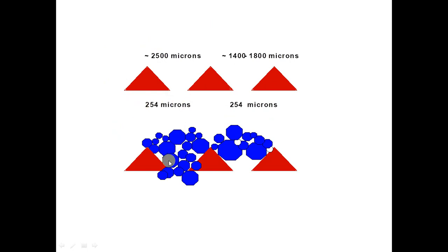Here, as you see, for example, if we assume that all of the bridging material is of the same size, as big as you can, like this, then at this time you will see a lot of voids between the large particles, and so it will let the filtrate be very high. But if we make a blend or mixture of the large particles, the medium particles, and the very fine particles, we will make a very strong filter cake. And I will discuss with you the mechanism of formation of this type of filter cake in the next lesson,